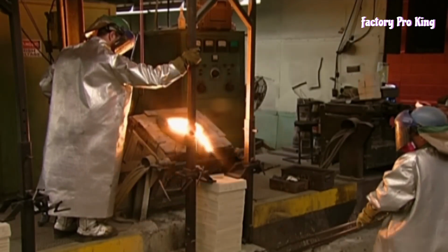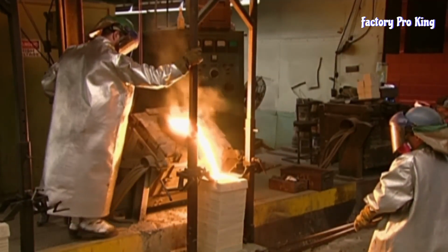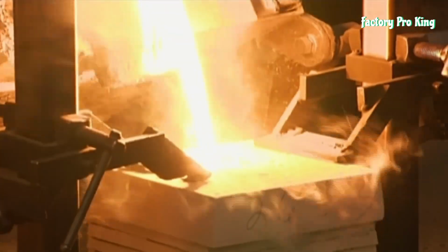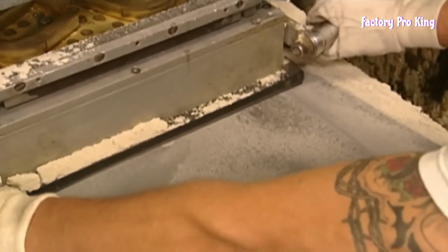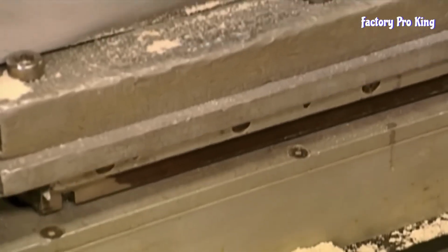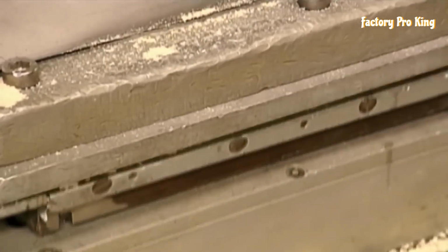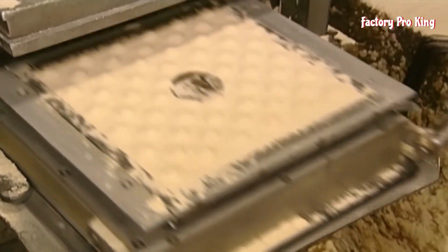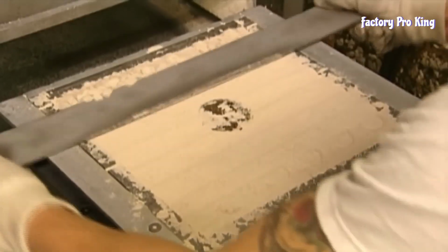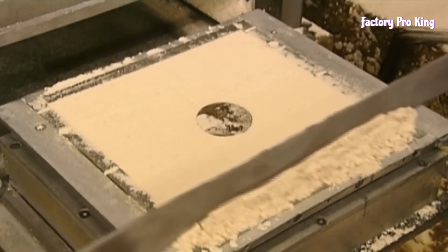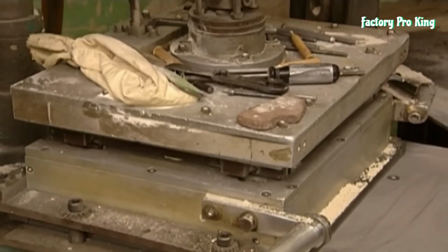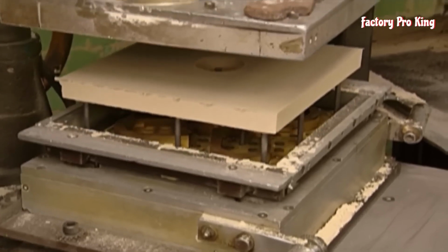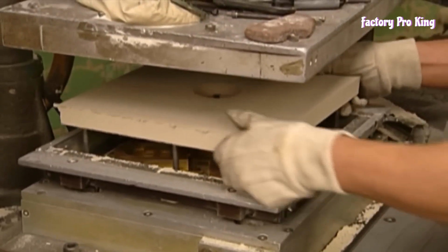The raw metals are cast into molds, usually made from sand, which can withstand high temperatures and is cost-effective. The process begins by creating a sand mold of the magnet shapes. They load the pattern of magnet shapes into a machine that fills it with sand. Once the pattern is filled, it's removed from the machine and the surface is smoothed out, removing any excess sand from the top. The sand mold is then chemically hardened by pumping gases into it.